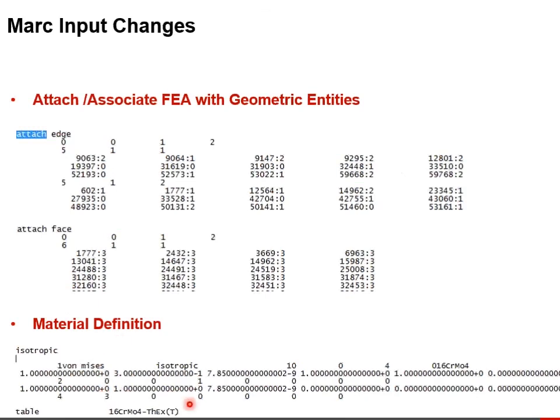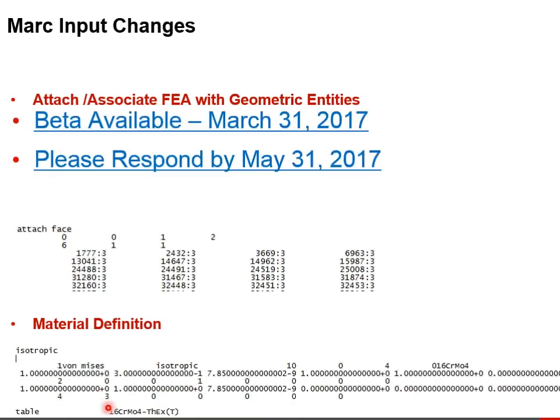When we see the material properties option, we don't see any more element numbers. We don't need to give the element numbers because when we gave the connectivity, we associated the material ID with the connectivity. In some sense, it's much closer to what we do with MSC Nastran when we have IDs on things like the CQUAD4 option. But in fact, it's a little bit more general than that because we can associate more types of quantities with these things.